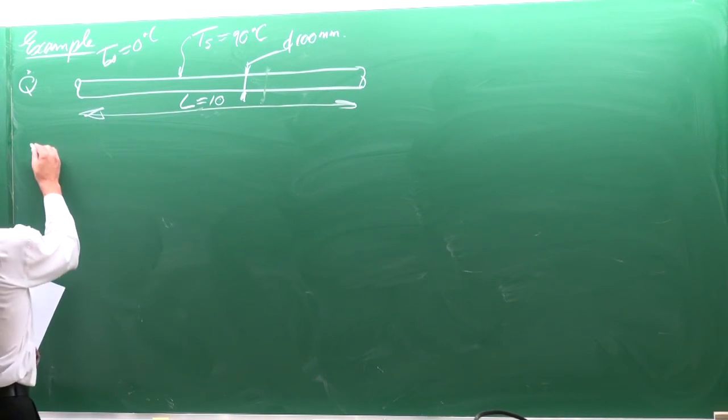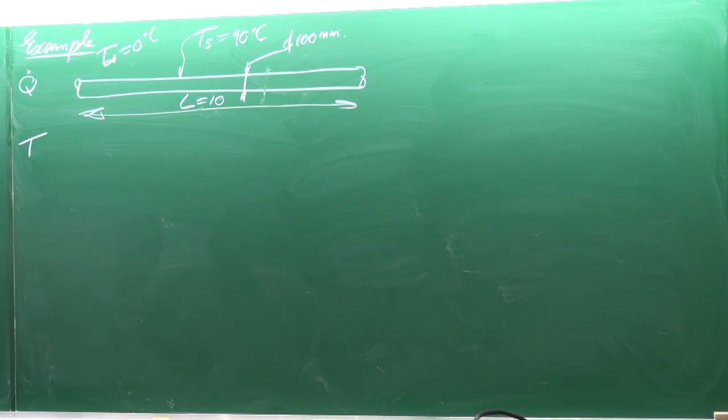Okay. So if we just think of Grashof numbers, we can immediately see there's a viscosity value that we need, there's a beta value that we need, so we know the properties are always an issue with these things. It's one of the first things that we need to get, because as soon as you get them, you can start doing calculations. So, we choose the film temperature as the point where we're going to calculate the properties.